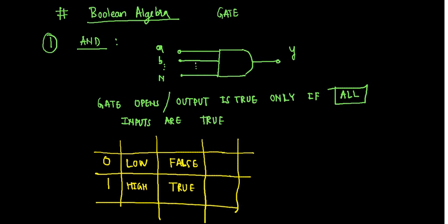Whenever I say true, it's 1. All these electronic devices, we say it as 0 and 5 volts. As technology is proceeding, this 5 volts is no more 5 volts. We are all targeting to reduce the power. So it's now 3.5 volts, even 1.5 volts. CMOS technology has the advantage of working with such a small voltage, power, current and power dissipation, and still your electronic devices work flawlessly. So this is one operation. An example would be, as I've given in the class, if both are interested then only it will be one. Or if you want to go for a movie, only if both your friends are there, then you go for the movie, and so on.